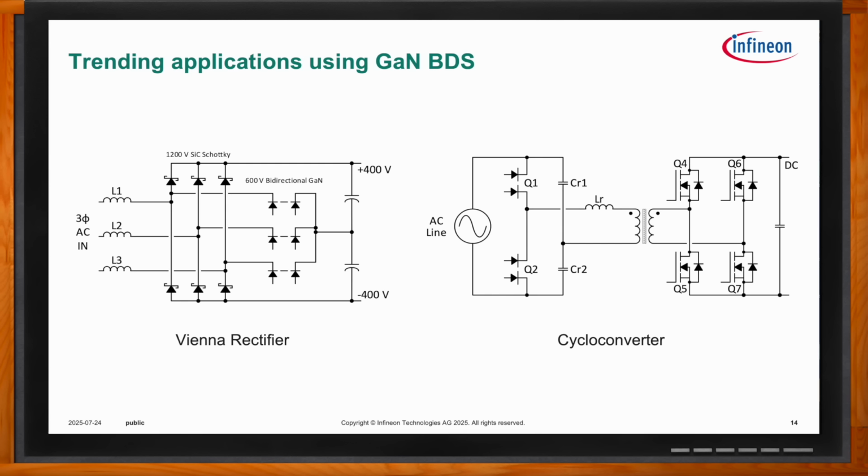Of course, what's not shown here is that between the AC line and the inverter, there's always an EMI filter, surge and spike suppression, and so on, as there is in any power supply. But the point being that because of the topology and because of GaN's unique capability to survive high voltage transients, this topology with GaN takes advantage of both of those in a very difficult situation. Rooftop solar is getting hit by lightning all the time. So this is one of the key advantages that we can use with this CoolGaN bidirectional switch.